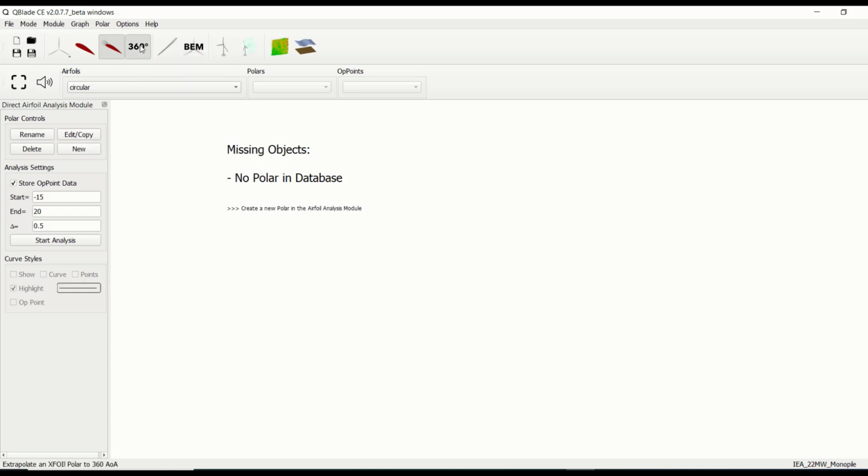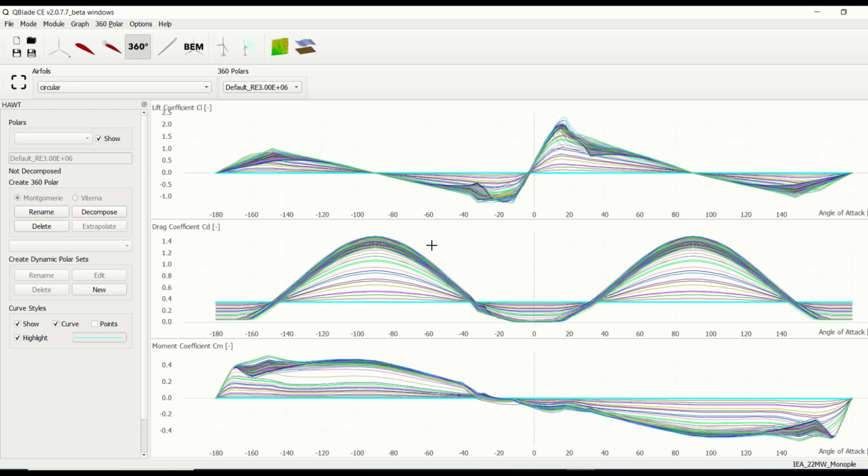You see here in OpenFAST, even in the user documentation and the other literature generated by Jonkman et al., they provided tabulated information on lift coefficient, drag coefficient, moment coefficient and other information for the different airfoils for their own 5 megawatt wind turbine blade. But here there are multiple lines, which are the different airfoils used for this 22 megawatt wind turbine system from IEA.